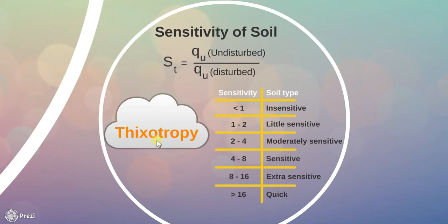If a remolded soil is allowed to stand without loss of water, it may gain some of the strength which was lost earlier. This strength loss, strength gain phenomenon is called thixotropy. The gain in strength is due to rehabilitation of the molecular structure of the soil.